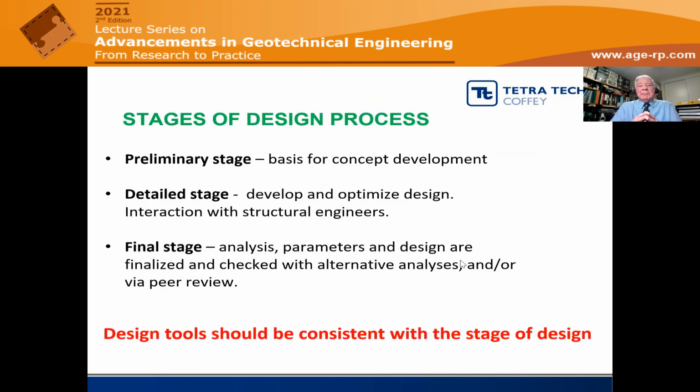Now, there are, in my view, various stages of the design process. The first of these is a preliminary stage, and we do this to try and get an idea of what sort of requirements our foundation system will have, whether we're dealing with shallow or deep foundations, and it's the basis for developing the foundation concept.